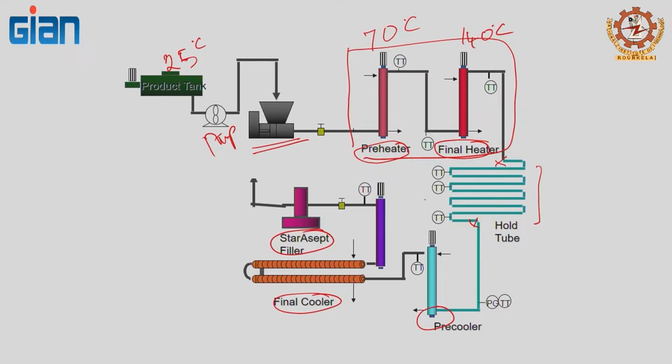That means maybe in one minute it may be delivering 3 gallons per minute, and the next time it may deliver 6 gallons or 5 gallons per minute. So, the flow rate is unpredictable. Positive displacement pumps are much more expensive, but they have precise flow control. If I set my flow rate as 3 gallons per minute, it is going to deliver consistently 3 gallons per minute.